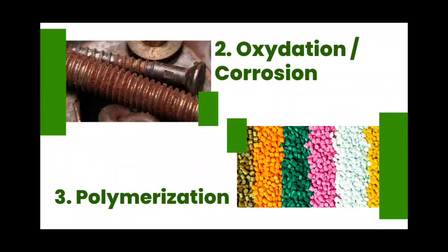The operating conditions for corrosion are the presence of an electrolyte, an exposed metal surface, and an electron acceptor. Corrosion occurs when a metal continues to oxidize. Rusting is a specific example of corrosion, which occurs when iron or steel reacts with oxygen and water. Corrosion can be prevented by coating, painting, galvanizing, or anodizing the metal surface.